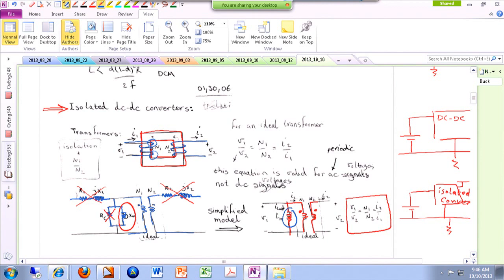Because of this low frequency, they use a different magnetic material. They just use, for instance, steel. So the magnetic core is steel, and they laminate it to reduce the losses. By the way, those transformers have a very high number of turns. For instance, your primary side may have 1,000 turns or 100 turns or something like that.